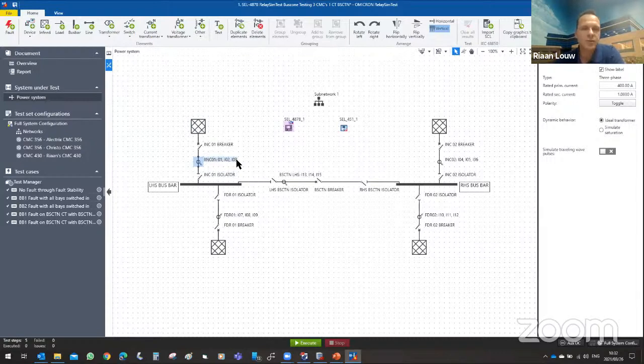And that means I just uniquely named them as per the terminal connections on the relay, IO1, IO2, IO3, continuing that sequence throughout the bays and also on the isolators of the CTs of the bisection. Then I have a couple of parameters that I can set here, CT ratio for the primary and the secondary, and then the one that I want to just quickly mention here is the toggle option.